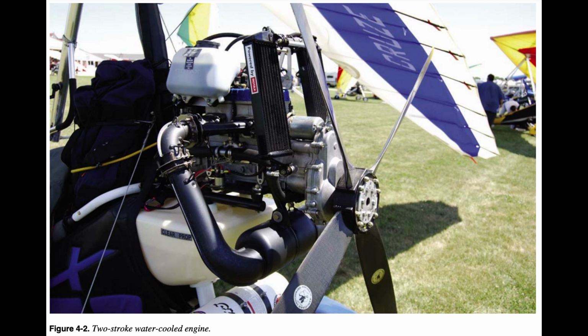Two-stroke engines. Two-stroke engines are commonly used in WSC aircraft. Two-stroke aviation engines evolved from two-stroke snowmobile and watercraft engines, the difference being that an aircraft engine is optimized for reliability, with dual ignition often installed for each cylinder. Two-stroke engines are popular because they have fewer components than four-stroke engines, which makes them less expensive to manufacture and lighter, thus increasing the power-to-weight ratio.